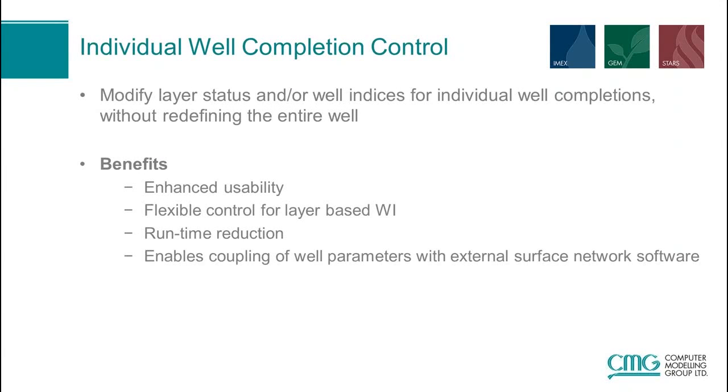Individual well completions. This relates to the ability to modify the per layer, per perforation status, or the well index without needing to redefine the entire well. Since the well is no longer being redefined, we have seen a reduction in runtime for some models. This also increases flexibility and allows for CMG to couple well parameters to some third-party external softwares which can control these accordingly. This, again, is available for all 3 simulators.